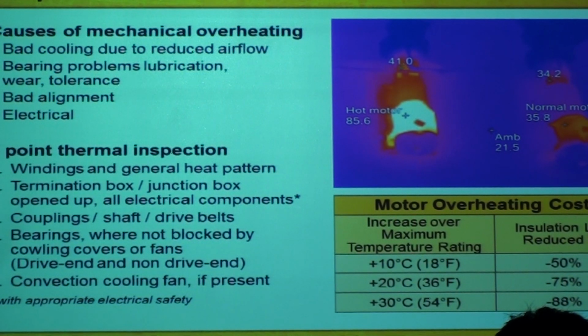Normal motor, bad motor. Both these motors are driving the same load, same conditions, but they have different temperatures. You don't need to be an expert to know that there's a problem there, right? If you have two systems exactly identical, exact same loading, if one of them's got an extreme temperature, something is definitely wrong. And the good thing is when you measure, again, like I said, with thermal imaging, you are measuring the surface temperature. But measuring the surface temperature gives you a very good indication of the internal winding temperatures.